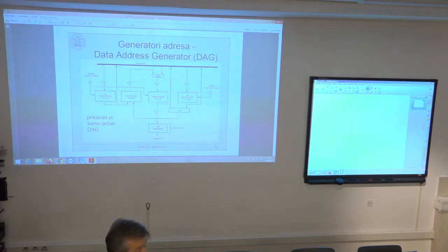That is useful if, for example, your application needs only a given number of modifications: update by +1 or by +2 or update by -1. So increment by 2 or decrement by 1. Then you can preload these values in these 4 registers, and simply invoke one of those registers as a modification register after the fetch instruction.